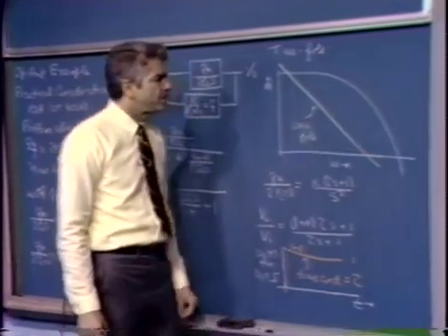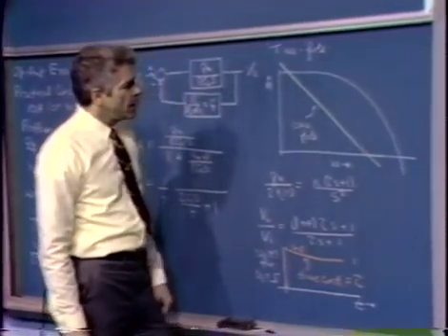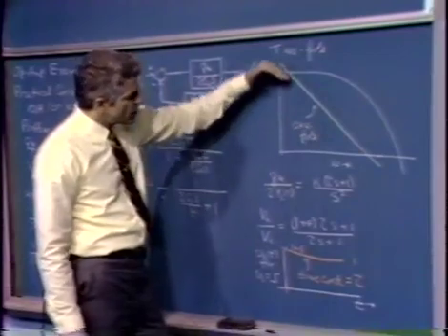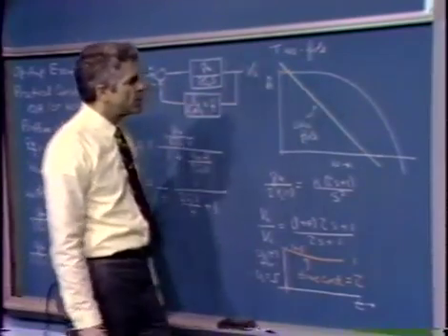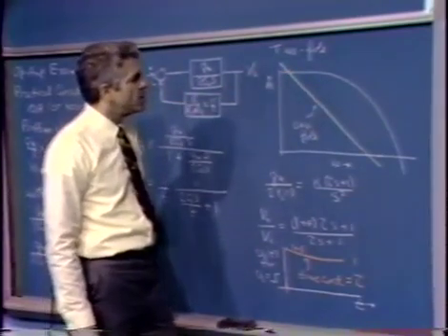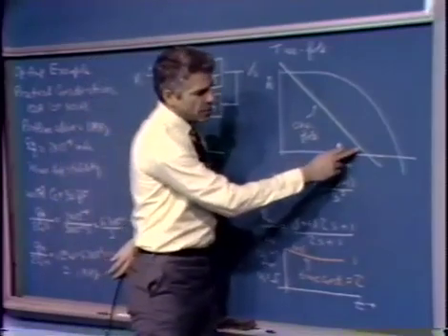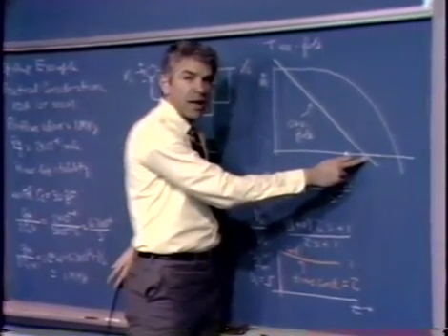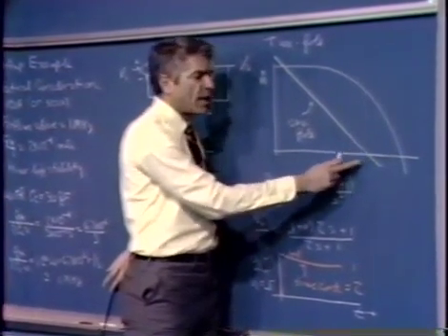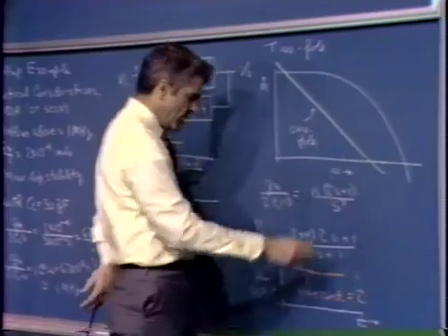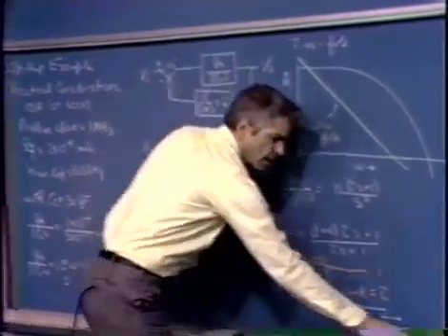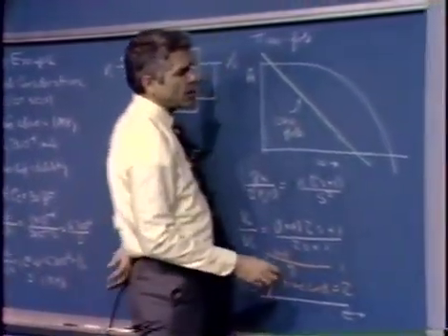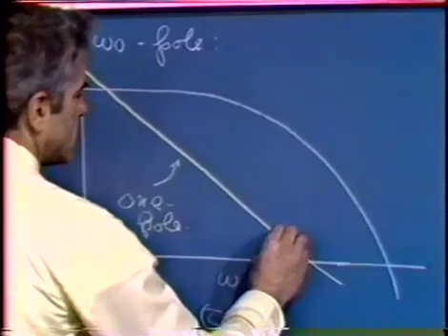Well, what would happen if we used a somewhat different kind of roll-off, a somewhat more heroic roll-off, if you will? Let's keep a single pole roll-off in the vicinity of crossover. Let's assume this is a plot of the AF product, so it includes F. Let's keep a single pole roll-off in the vicinity of crossover, but let's roll off as 1 over s squared at lower frequencies.